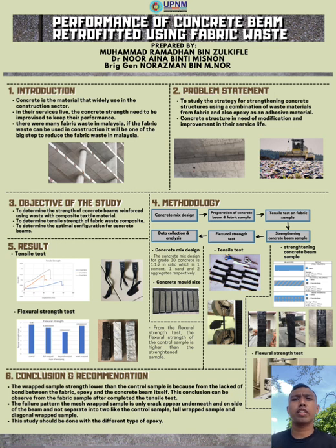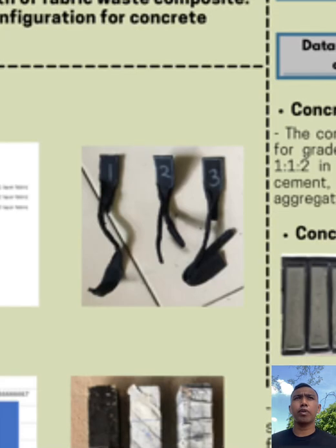This conclusion can be observed from the fabric sample after the tensile test, because we can see the fabric layers with epoxy did not separate completely, and the layer of separation is the layer with epoxy, and the layers that still stick together are in a high percentage of the fabric only.